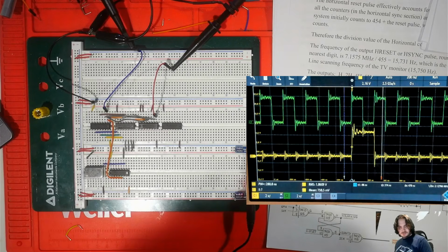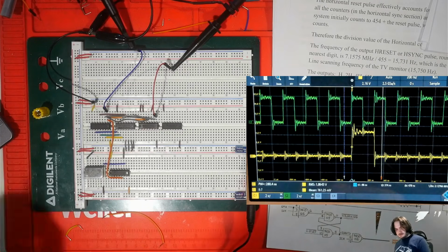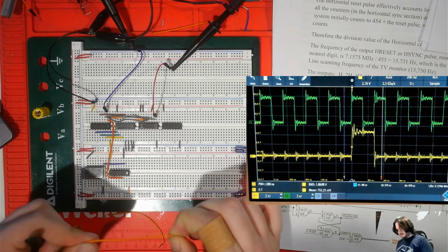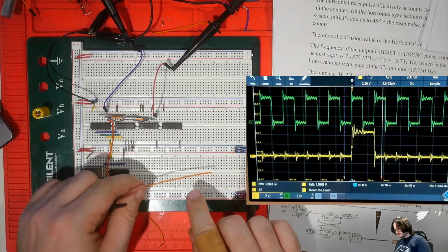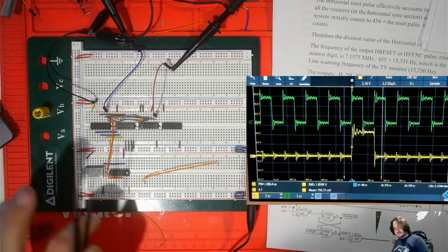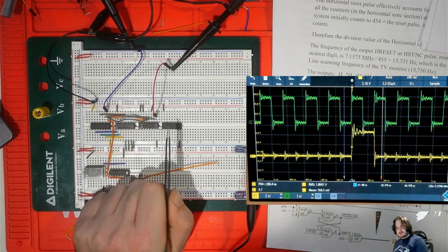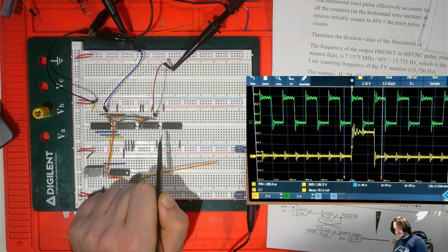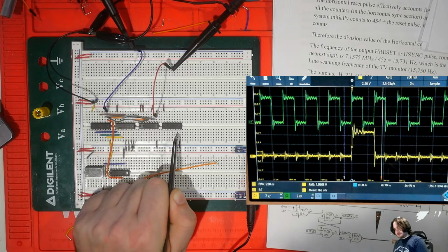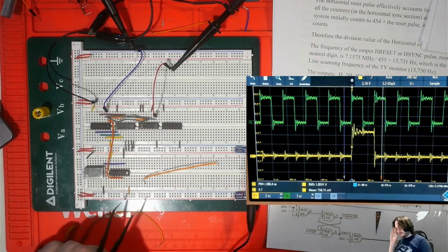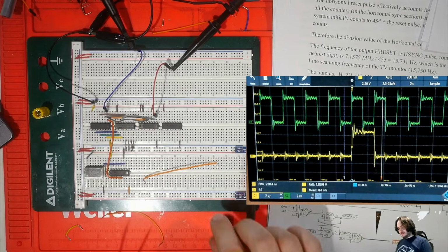This is another jump size that we don't have exact wire lengths for in the kit. But I've pre-figured out which ones can reach. So, without even having to check the datasheet, I know that the pins on any 2-input, 1-output logic gate go input, input, output, input, input, output, and then on the top here, input, input, output, input, input, output. So it's fairly easy if you know it's just a basic logic gate to count that out.